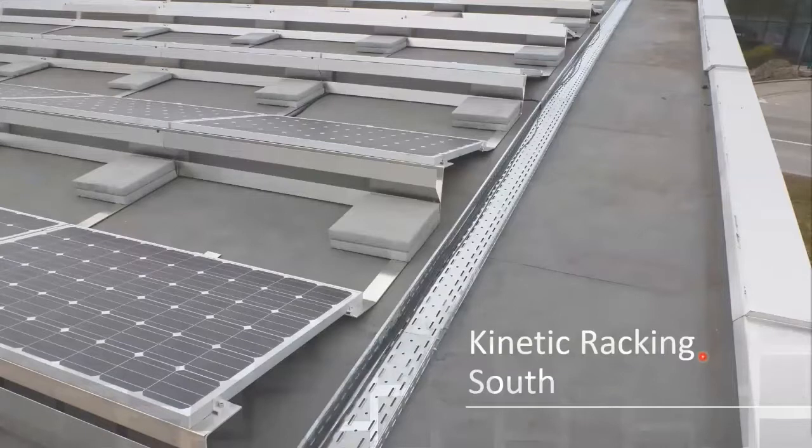The next one we've sold and you'll see in this marketplace are flat roof. Very common in commercial, and really they only make sense for commercial. You get into small residential systems, not really applicable because unfortunately with flat roofs, it's economies of scale, in the sense you need multiple modules to create a bridging effect to self-support or self-ballast. If you have a small 10 kilowatt deployment on a residential flat roof, you'll need quite a few penetrations to hold that on. Whereas if you interconnect all these modules on a commercial roof, the system gains strength and stability by having more modules connected to it.